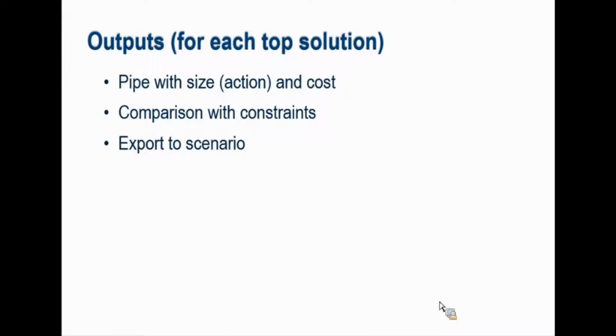And then ultimately what you're trying to do is find a solution that you really like, that makes a lot of sense, that you want to promote or export as a scenario, and then go run that design against a lot of other design tests like fire flow analysis, criticality, and the like. Maybe water quality or something, because you've got really large diameter pipelines in this design, and you want to make sure that that's not going to have an impact.